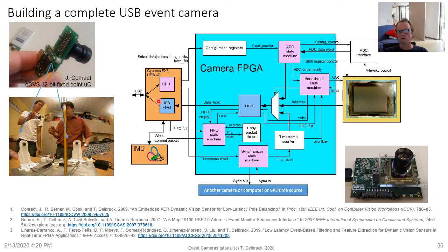There's at least 4 of them here that are taking the events from the FPGA that are coming from the Davis chip and buffering them in a round-robin fashion to optimize the transmission of the data to the host computer, because the host computer may not actually poll this bus that often, right? It gets busy doing other stuff. So these FIFOs are like capacitors for information.